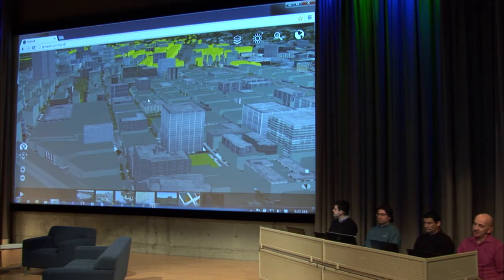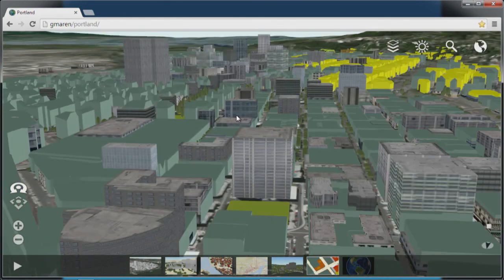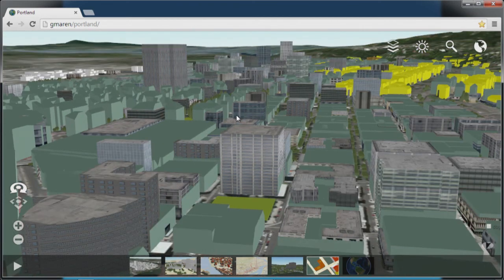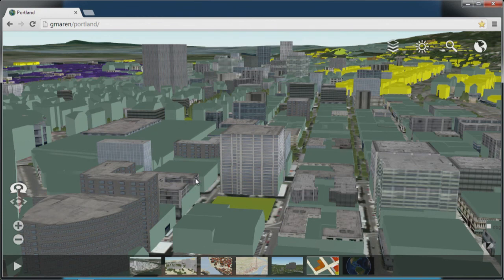And then, as you see here, we have the rendition of the city, but we also have these spaces or shapes, and they're not just volumes, but they actually represent the planning space and setbacks that the rules and regulations and the zoning regulations for the city have defined. And you can then look at this and go, okay, well, what buildings are outside of the zoning regulations, and then also, well, how accurate is my model?